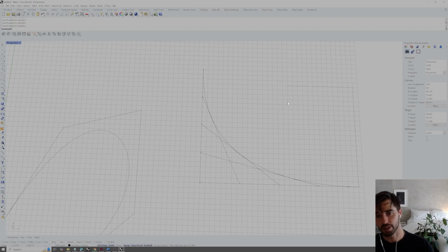Or let's think about it like a polyline. A polyline is only defined by those vertex points, whereas a NURBS curve is defined by all of this math going into it. So a NURBS curve is much more computationally intense, just like a polysurface is much more computationally intense. And we'll get into what a polysurface exactly is in a moment. If we were to do a degree 3 curve, we'd now have to increase the number of segments. So we'll have to use 3 segments this time.